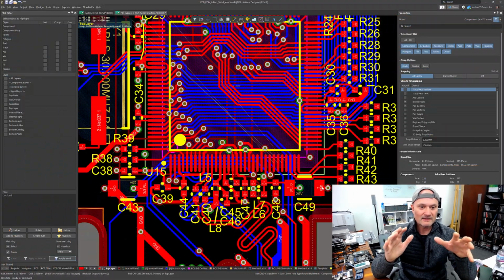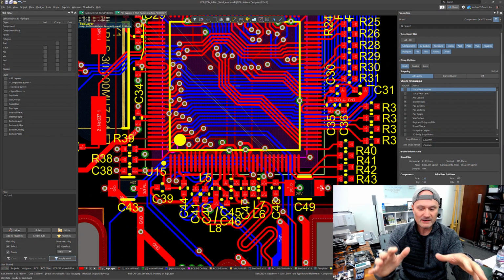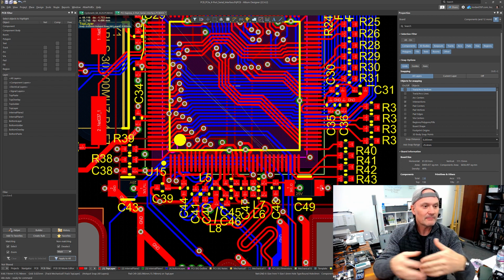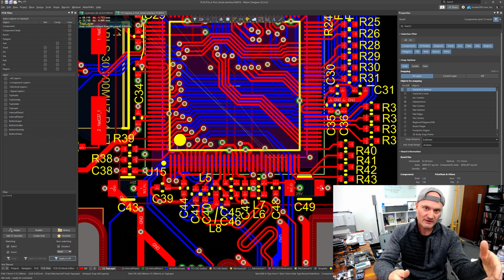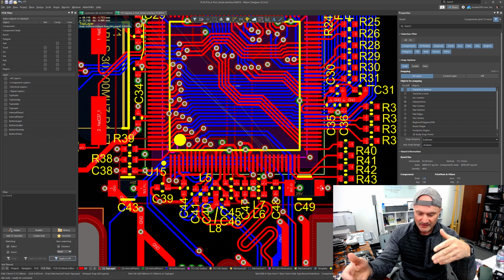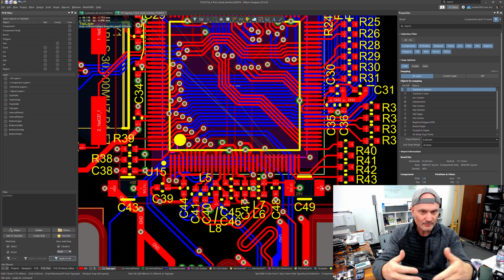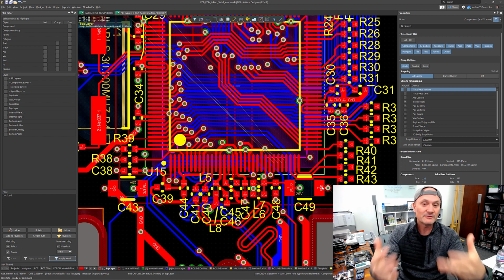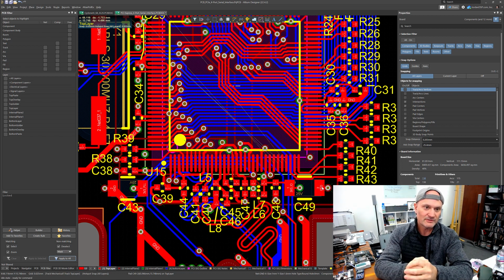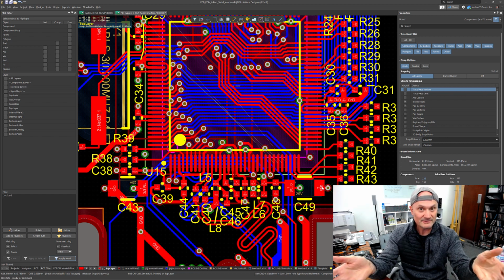Almost everything you do in Altium Designer, and this is a valuable tip for anyone using this product in the PCB editor, right? Almost anything you do is governed by design rules. Why is that? Because there are manufacturing and assembly rules and constraints, and there are things about the printed circuit board fabrication process that we have to adhere to, to make sure we get a good result and that the PCB factory can actually build our boards with high yield. In other words, keep the costs low.